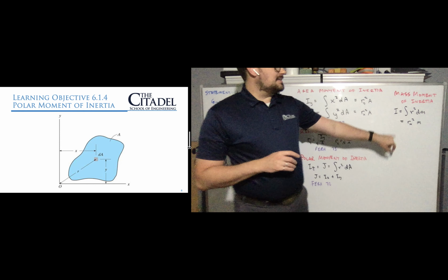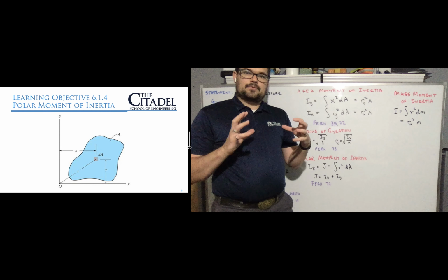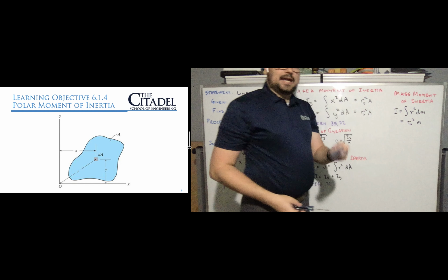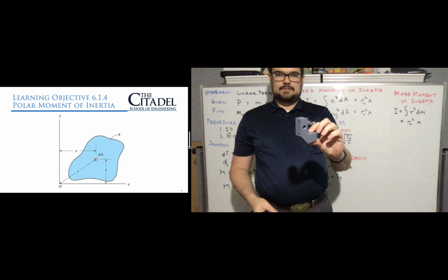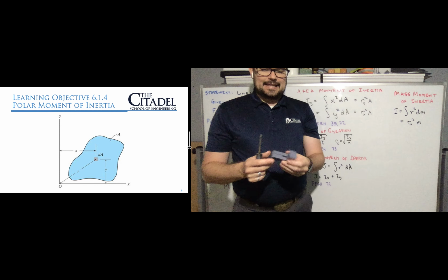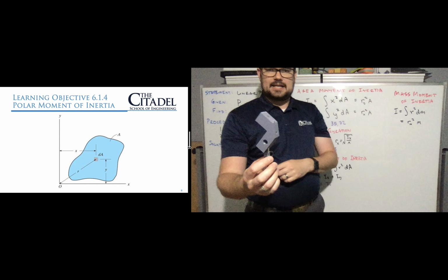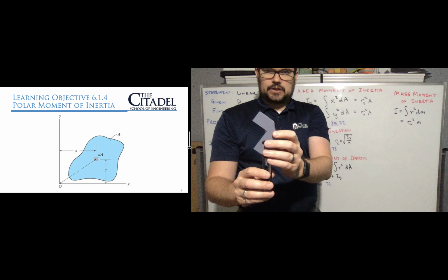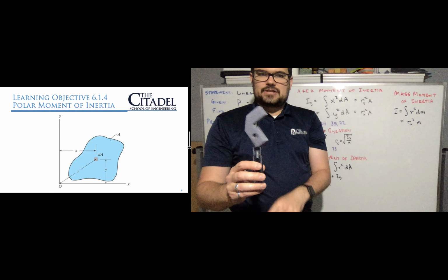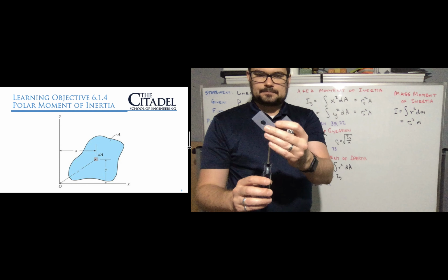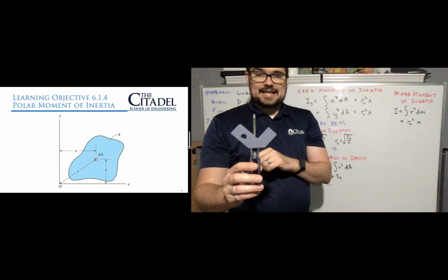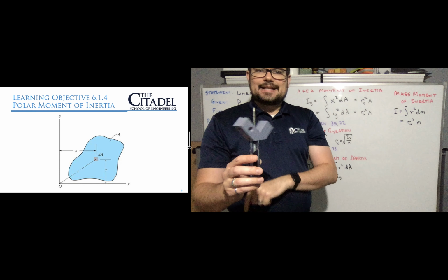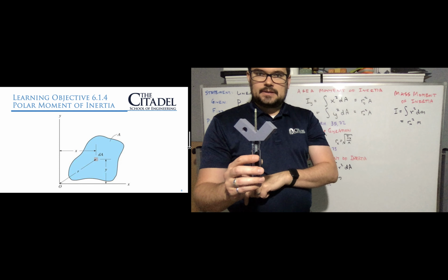And so maybe this is a concept that you're actually familiar with and you can think of from a mass point of view. And in fact, next time we'll look at a shape like this, right? And we can see that if we pick an axis that looks something like this, my axis is vertical off the screwdriver. All the mass is very close to this axis, and so it spins pretty easily. But if I look at this axis, the mass is spread out. It has a much greater radius of gyration, and so it's going to spin more slowly, if y'all see that.